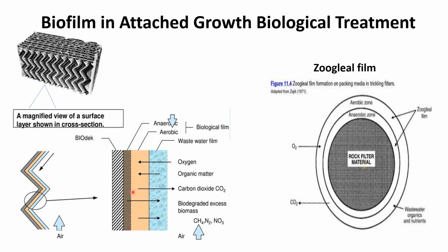So the microbial growth on the surface becomes depleted of oxygen, and growth of anaerobes is encouraged. The top layer of the slime layer interacts with the organic material in the sewage water, and there is enough oxygen, so aerobic growth is encouraged on the outer layer of the slime layer.